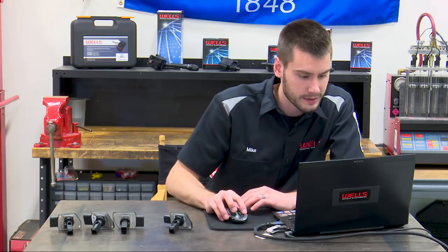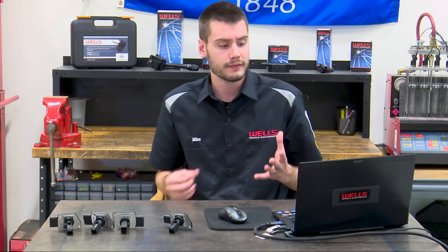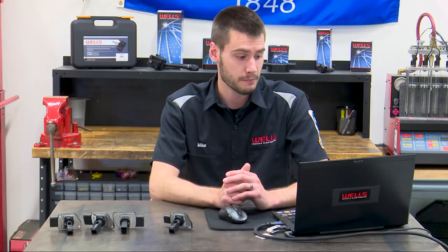OzStar came on and said, now I have to try that 80% rule. And that's something that I've been playing around with a little bit here, and I've found that it's pretty accurate. That's that 80% of your vehicle horsepower should be roughly your mass airflow grams per second. I've seen that it's pretty accurate so far. I don't know that I would use that as my only justification, but I think it is something interesting and something that kind of helps maybe move things lower down the list if you're on your diagnostic checklist, okay?